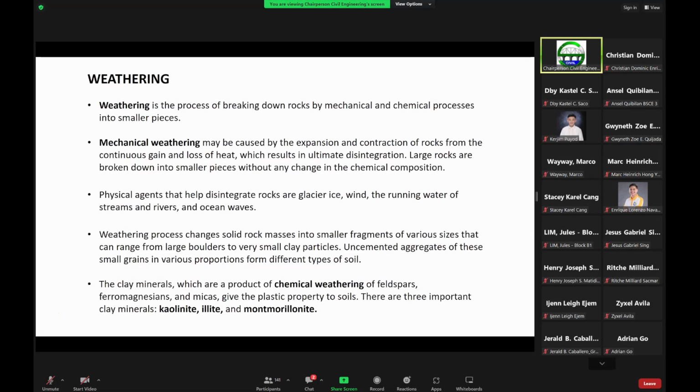Per layer, for example from 1 meter to 1.5 meters, we usually describe the material that is being recovered from the drilling operations. Normally we describe them as either boulders or cobbles, or sands, shales, clays, and gravels. So we describe that per layer, per depth.